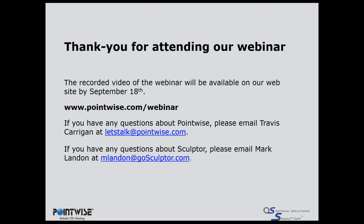Yes, and because Sculptor is morphing things volumetrically through what we call the trivariate volume, the movement of all of those nodes with respect to each other is very smooth, so that we maintain the cell quality, we maintain the boundary layer thickness, we maintain the orthogonality, and we also maintain cell quality out into the flow domain, so that there's no need to remesh, there's no need to smooth. It all happens during the deformation.